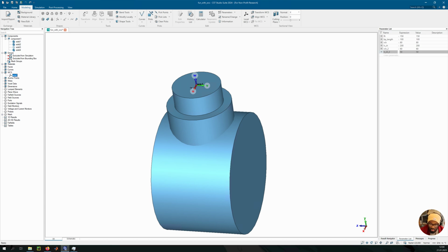And if I want to model on top of this, then I have to select that it should use the local coordinate system. Just as an illustration, if I do not select this and I wanted to model, you already see that the coordinate system it is using is still the global coordinate system, which is your XYZ, because even though it's showing it's selected, I still have to select it from here so it knows to use the WCS1.